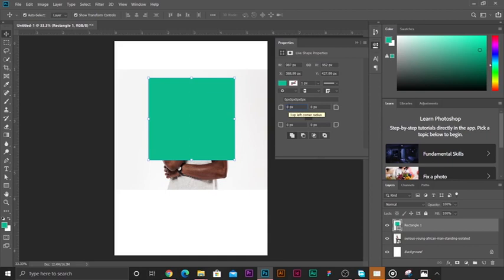Now whatever number I put here, let me say the top left angle should be 10 pixels. Once I click enter, you see how every single angle has turned to 10 pixels each. Do you know why? It's because of this link here. It shows that all the angles are linked together, so whatever change you make to one edge affects every other edge or angle.